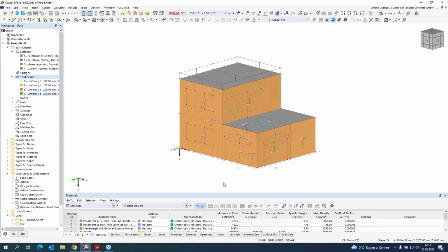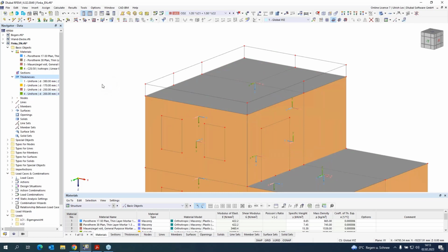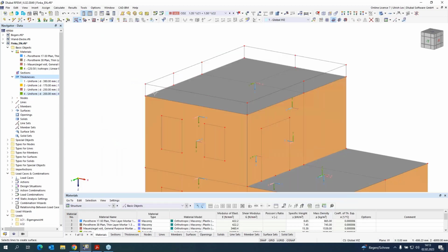On the roof, or for the roof flat, the first thing we have to consider is if we work with masonry walls. If you have a masonry wall and a roof slab, then the slab always wants to turn up in the edges. That would cause damage in the masonry. That's why we have to create something so that the slab cannot turn up. In this case, I want to create an attica in concrete so that this turn up cannot happen.